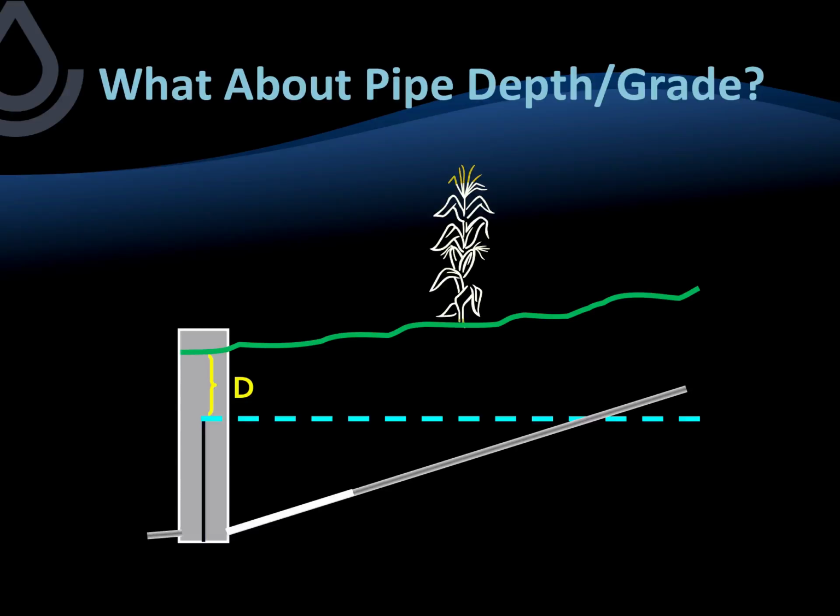Now, for this last option here, this does matter, obviously, because now we have a desired water table depth that is below or deeper than the tile on the upstream portion of this particular pipe. So in this case, it would matter. If my zone were considered to be extending all the way to the right in this figure, part of it is not going to be functional at certain water table depths.